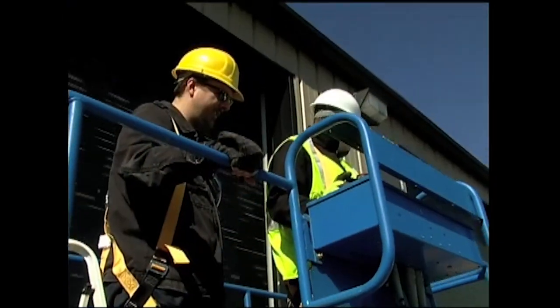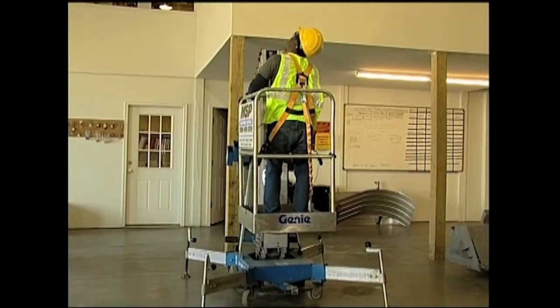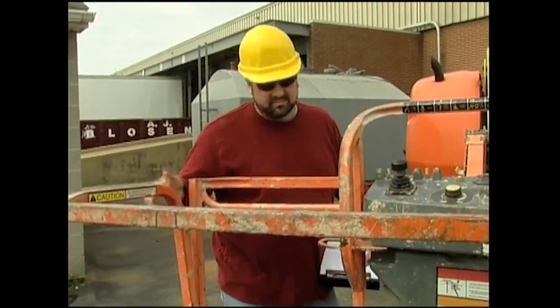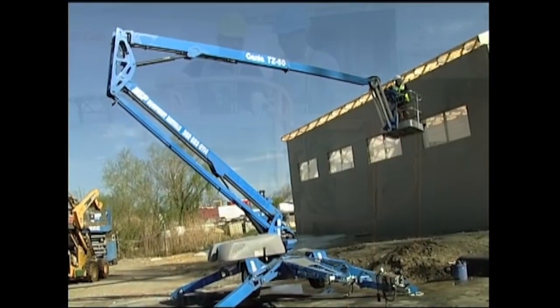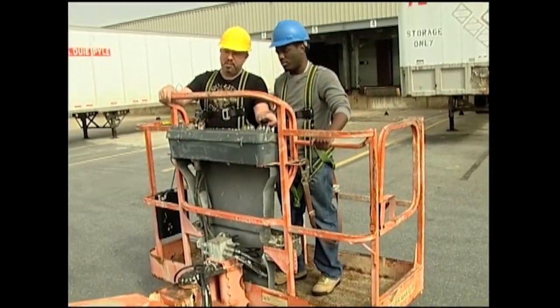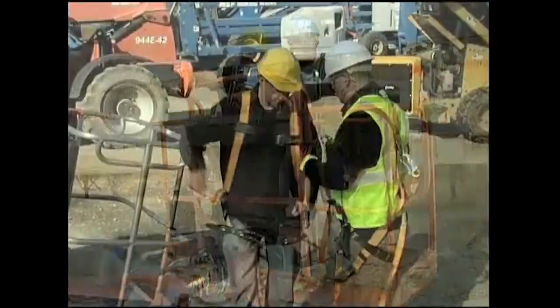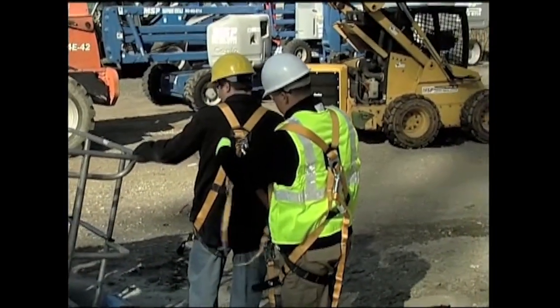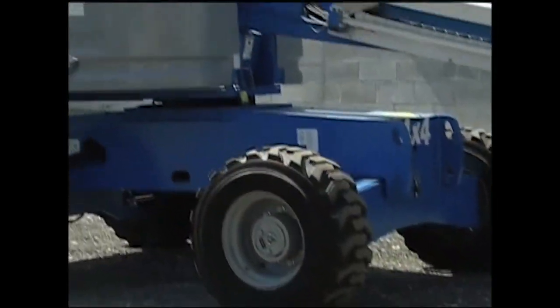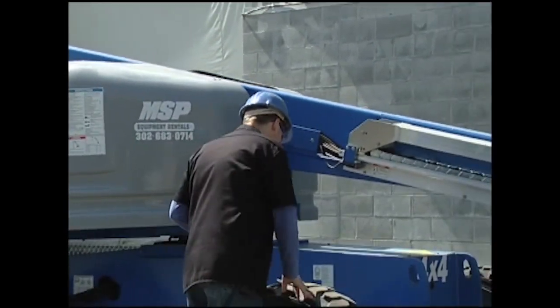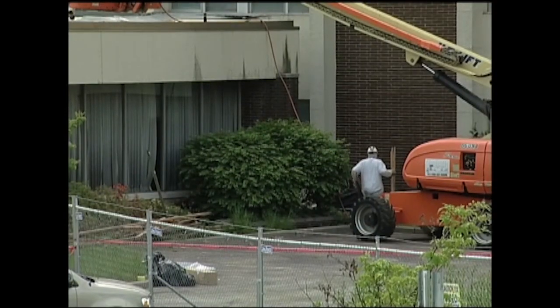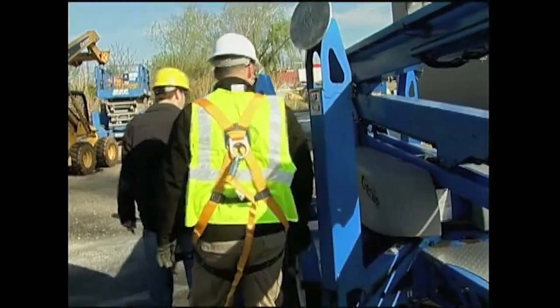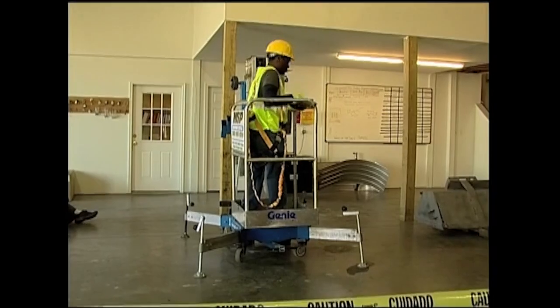Aerial lifts can help you reach places that you'd never be able to reach safely without them. But they can be dangerous if you don't know how to use or work around them properly. Let's review. Make sure you're trained to use all of the aerial lifts you'll be working with. Know the hazards associated with aerial lifts and how to avoid them. Inspect an aerial lift for damage or unsafe conditions before you use it. When you're working on the ground, be aware of the hazards aerial lifts can present. Know how to properly set up and operate your lift, as well as how to break it down and return it to its home.